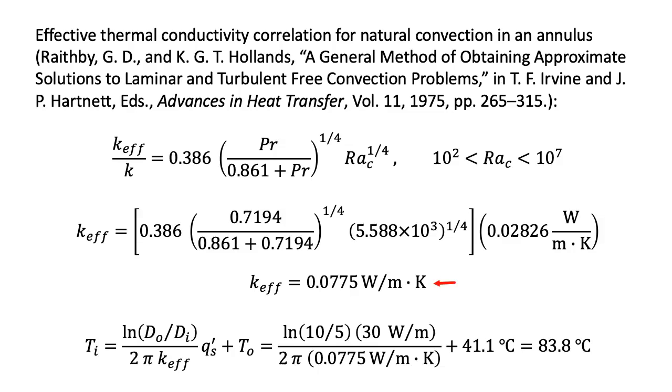Substituting in values, we get an effective thermal conductivity of 0.0775 watts per meter Kelvin and an inner surface temperature of 83.8 degrees Celsius, which agrees with our initial guess, thus confirming that the solution has converged. Again, if we had guessed something else, our temperatures would not agree, and we would repeat the calculation until they did so.